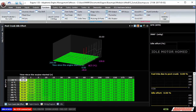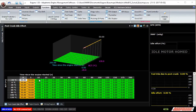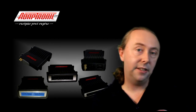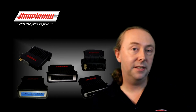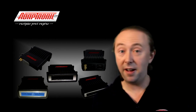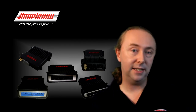So just like all the other 3D tables, the post-crank idle effort will be interpolated between these values. So if you have 10% at 10 seconds and then 5% at 20 seconds, at 15 seconds it'll be 7.5%. Now, whenever this value read from the table is greater than 1%, the ECU will not go into closed loop mode. The reason is that the percentage is there to cause the engine to flare a little bit and go higher than the target idle speed. So you don't want the ECU to go into closed loop idle in this condition.